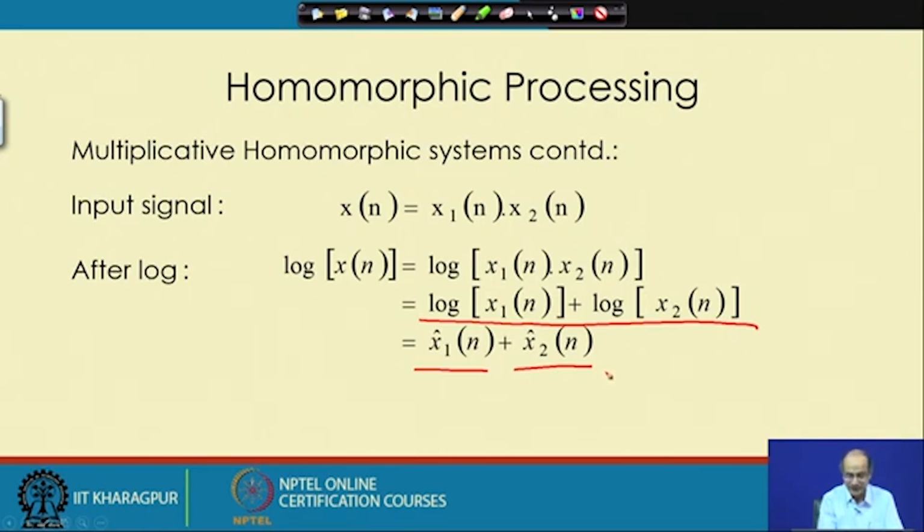For example, we look for filtering to separate out high frequency noise or power frequency noise from the biomedical signal of interest, and there we first assume that the signal of interest and the high frequency noise are separated in the frequency domain.